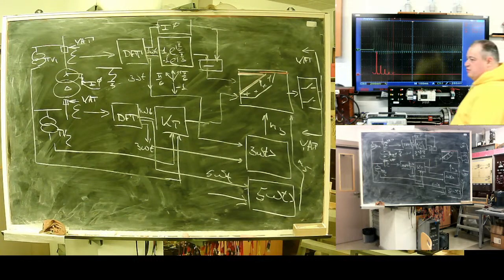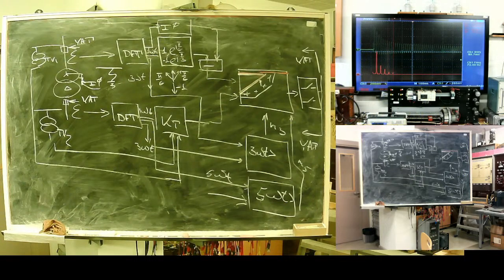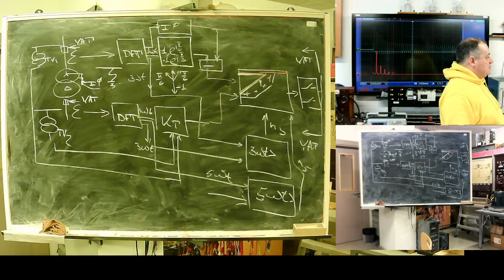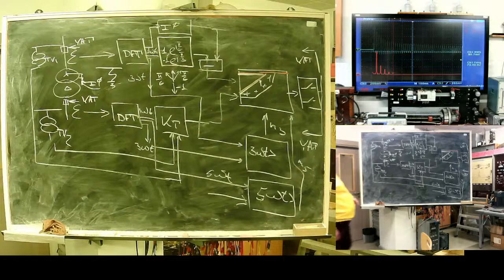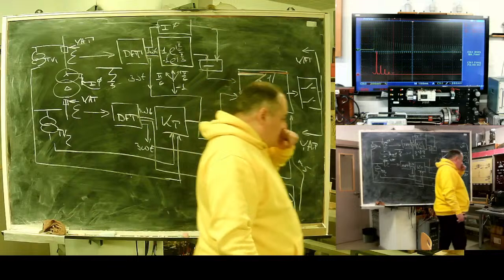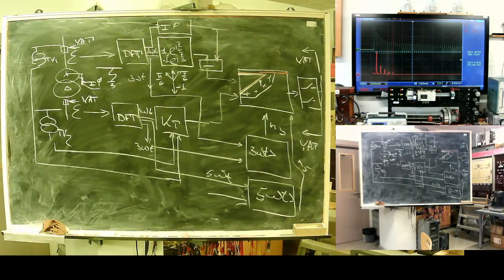Magnetic resistance of the central leg differs from the side legs. One problem, another problem: steel is not ideal, transformers are not ideal, and network load isn't 100% symmetric. This limits this area, this gap is limiting. It's good protection, but it's not sensitive enough.